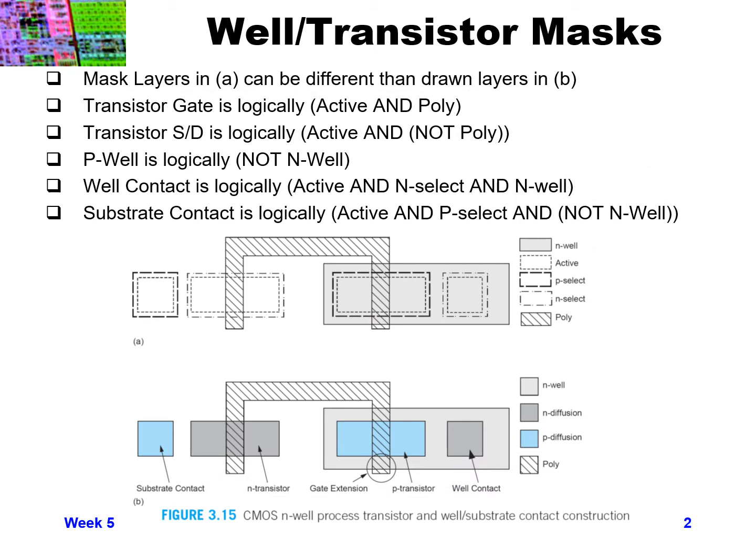While talking about design rules, I should also mention the design rules are designed to make sure you can generate the masks that you need and then pattern those patterns onto your wafer using your photolithography steps as you desire.